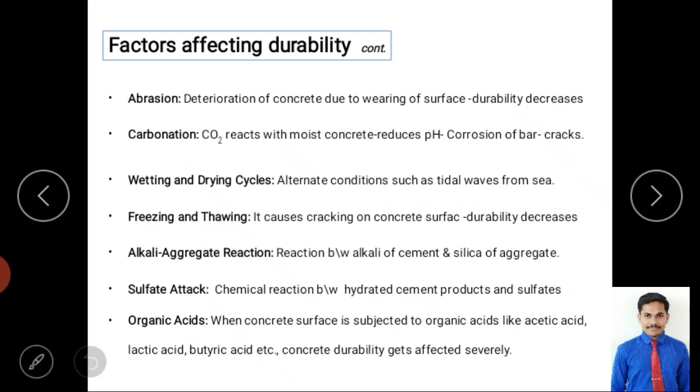Abrasion means what? Wear and tear. So where will you get wear and tear? Where you have more wind blow, but exactly these kinds of effects occur in streams. For example, when you are constructing channels, like drainage, gutters and channels for streams, due to the silt and some stone particles in the water, it may wear and tear the bed